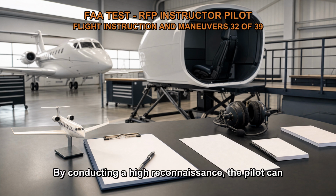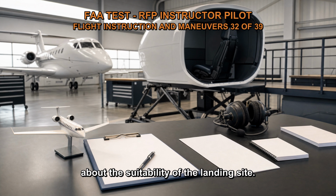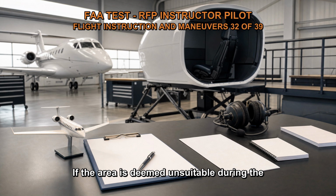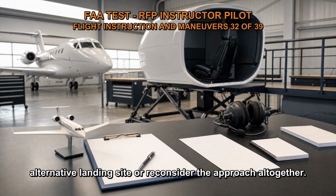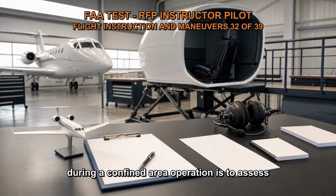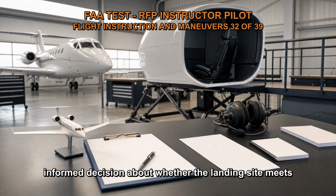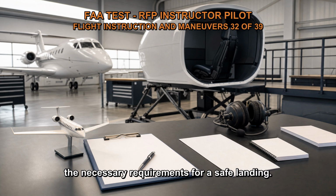By conducting a high reconnaissance, the pilot can gather critical information to make an informed decision about the suitability of the landing site. If the area is deemed unsuitable during the reconnaissance, the pilot may need to identify an alternative landing site or reconsider the approach altogether. In summary, the primary purpose of high reconnaissance during a confined area operation is to assess the area's suitability for landing. This ensures that the pilot can make an informed decision about whether the landing site meets the necessary requirements for a safe landing.